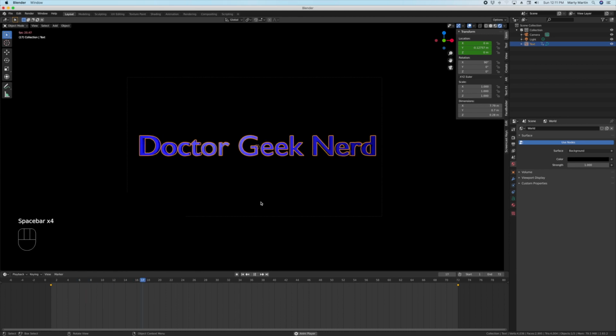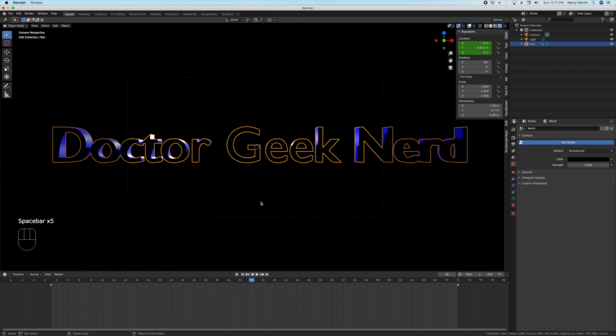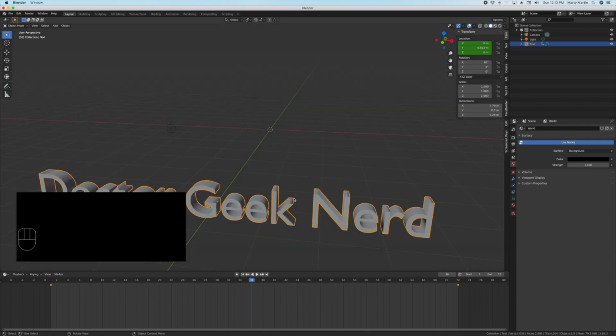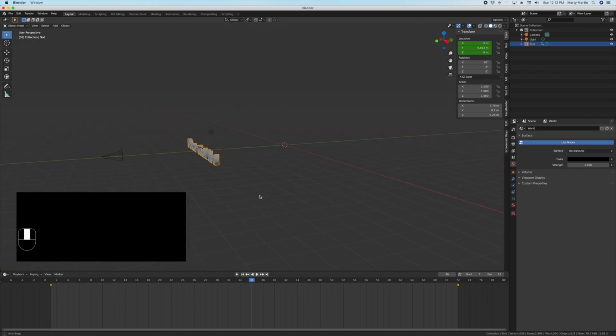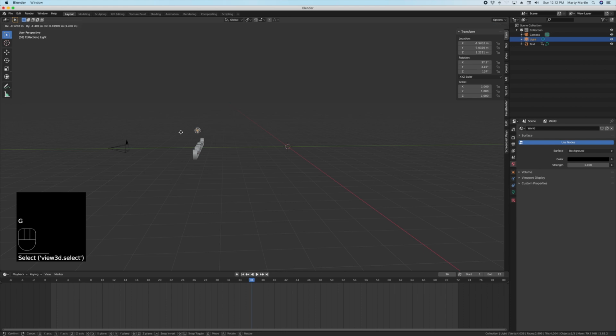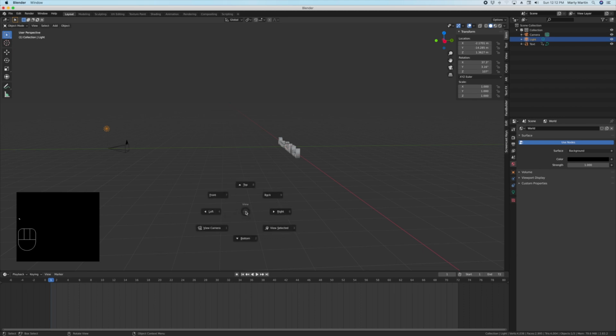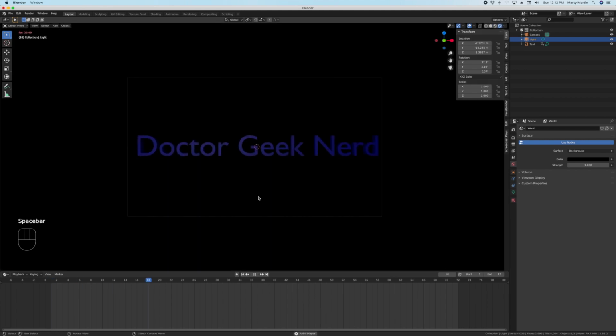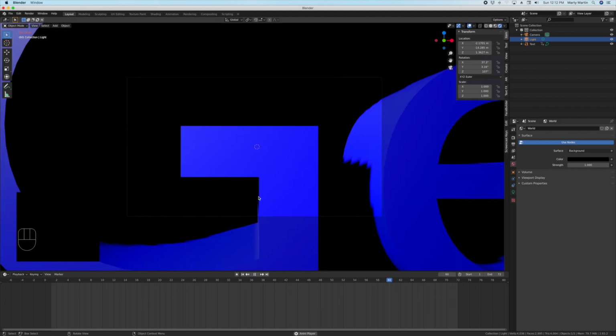If you don't want it to go dark, right here at that frame, just move the light back. In fact, let's do that. I'm going to hit Z and go to solid view real quick. And yeah, let's move that light source all the way back here. How does that affect our animation? Go to rendered view real quick. There we go. And it goes past the camera.